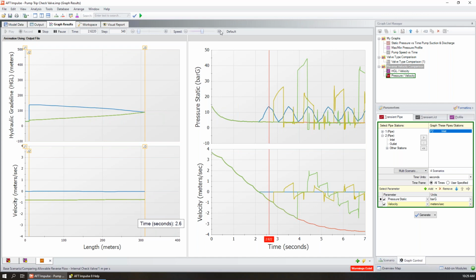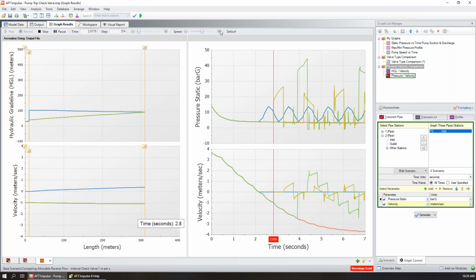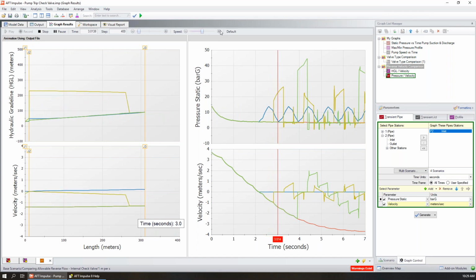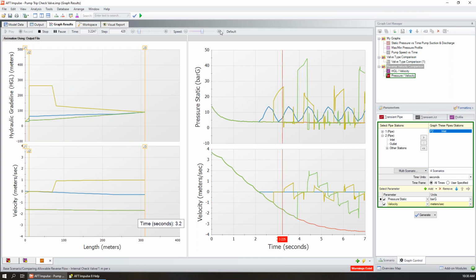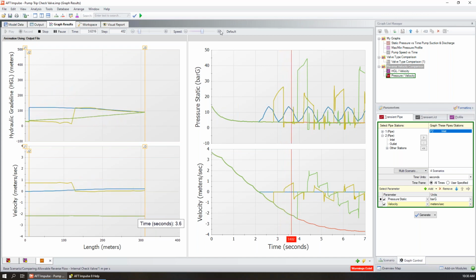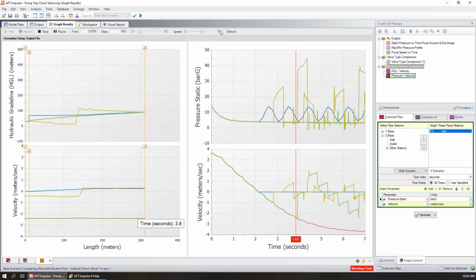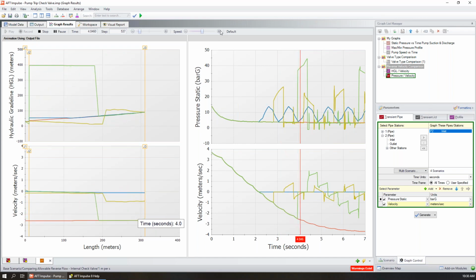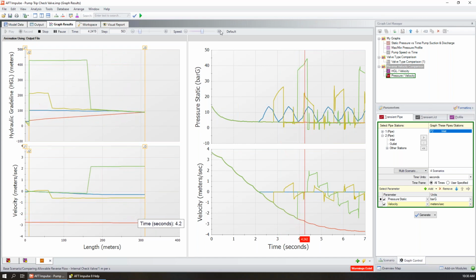So we're coming up on our first closure, this ideal closure, where you see that gradual increase in pressure. It's not a kind of spike event. There we see our significant increase at -1 meters per second. And then if we wait for our 2.5 meter per second closure, there we can see how that high pressure is transmitted through the system.